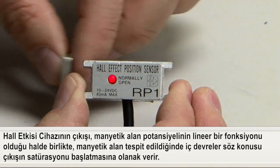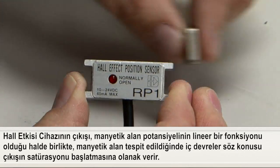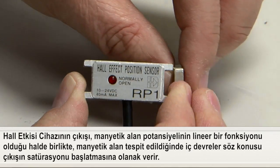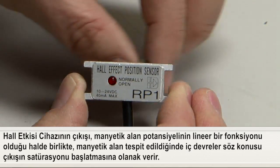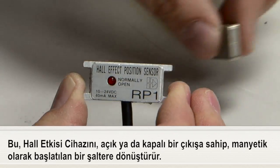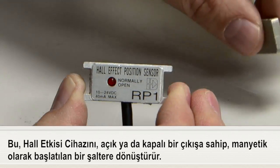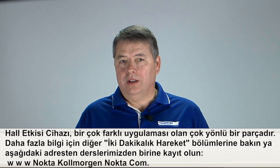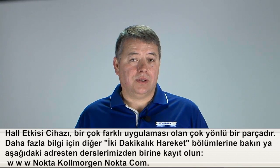While the output of the Hall effect device is a linear function of the magnetic field potential, internal circuitry allows the output to trigger to saturation when the magnetic field is detected. This basically turns the Hall effect device into a magnetically triggered switch with an output that is either on or off. The Hall effect device is a versatile element with many different applications.